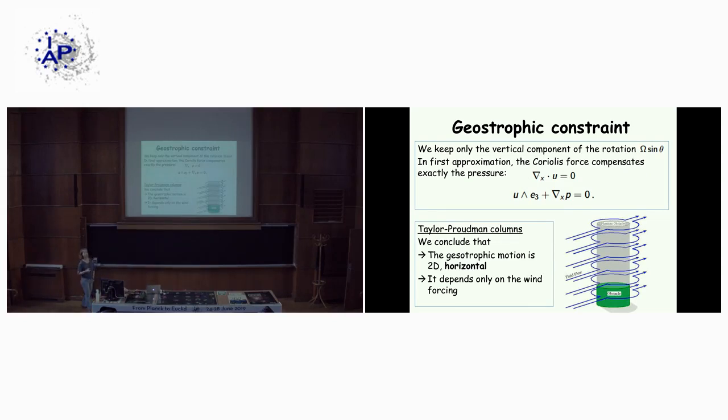So what I say is that if in this system the dominating force is the Coriolis force, then in the equation what you have as main terms, of course you still have the incompressibility condition, okay, your fluid is still incompressible, so you keep the fact that the divergence of u is equal to 0, and then in the equation for the evolution, the main terms are this term here, which is the Coriolis term, and of course you still have to keep the pressure term, because this is something which just ensures that you can keep this incompressibility condition.